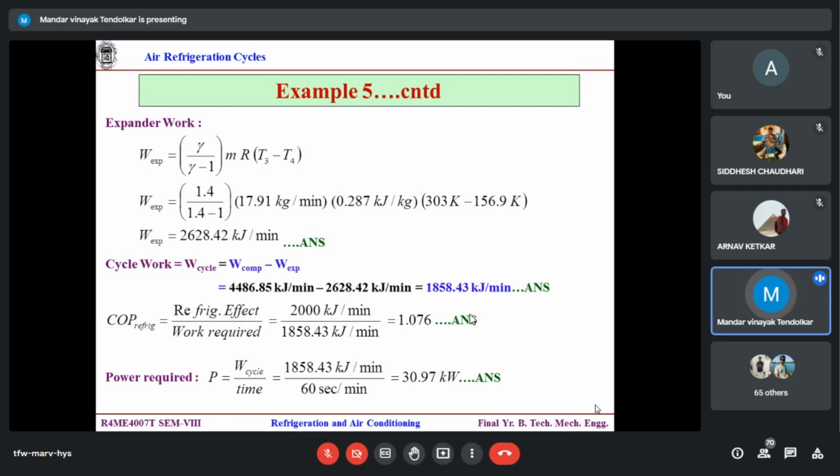And for vapor absorption, it is a fraction lesser than 1. Always keep these values in your mind as a cross check. If your COP values go wrong, that means there is some mistake in your calculations. You can cross check.